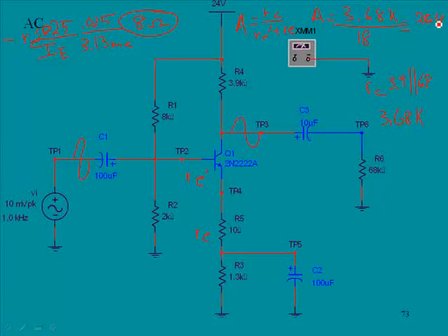And so what we'll experience here is if this signal comes in, and this is 10 millivolts peak, then the output should be 204 times larger. Now, what you can see here is if the value of this component is increased, say we increase this to, I don't know, 100 ohms, it'd be 10 times greater, but then our gain would be drastically reduced as well, because now this would be 108, so our gain would be much lower.